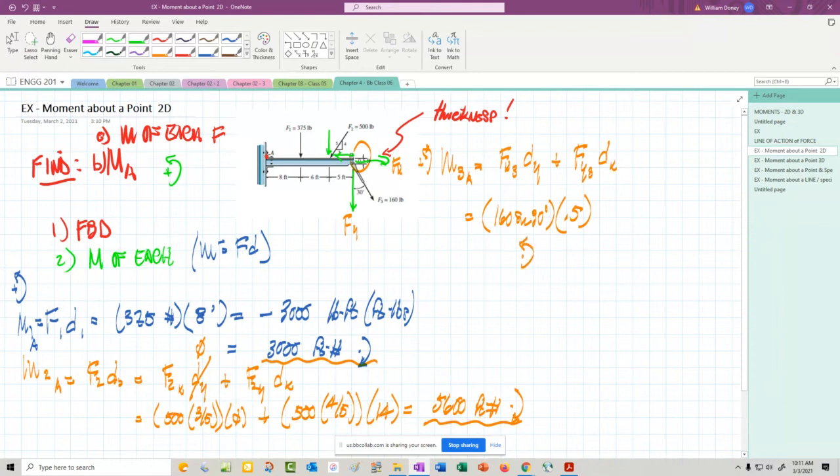This one is trying to rotate it up, so that would be a positive. And the force Y is going to be 160 cosine of 30 times the distance x of, I think, 19 feet. And since that's trying to pull it down, which would be negative, we want to make sure we have the negative right there. Negative there means we have to put it there since we call positive counterclockwise. I think this comes out to be a plus 40.